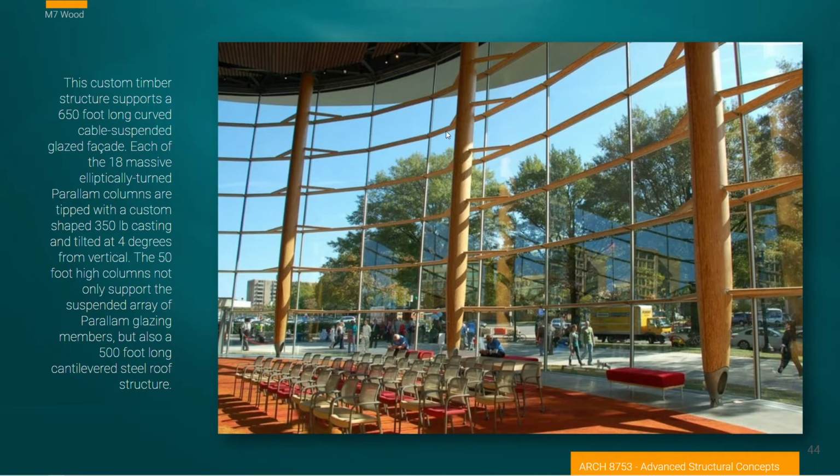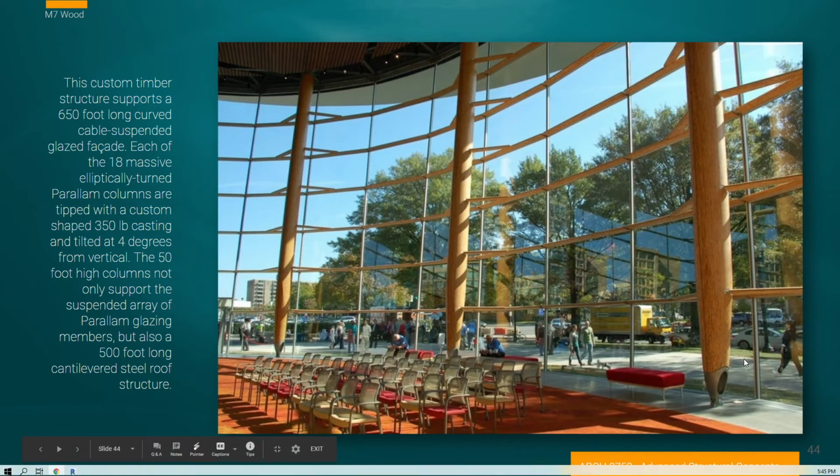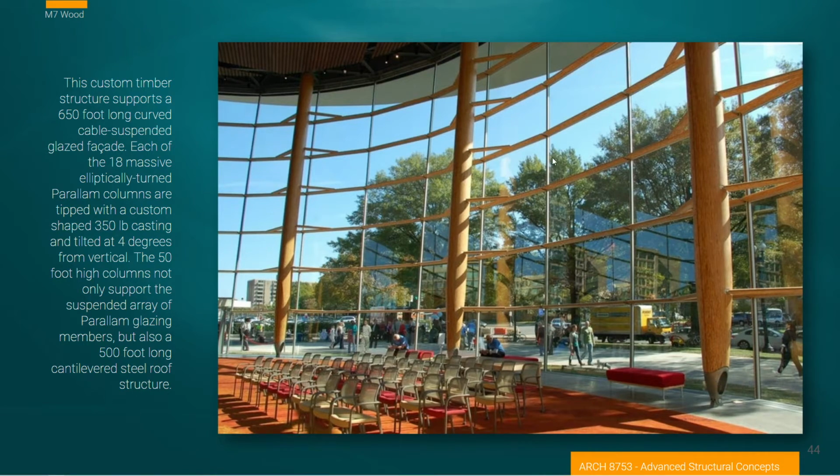Here we have really massive laminated columns with obviously really high bearing capacities. I'll show you in another slide here the beautiful connections of these columns. It's interesting to note these wings that are coming off of here that are actually being utilized to help stabilize the glass curtain wall, giving a great sense of transparency to the whole space.